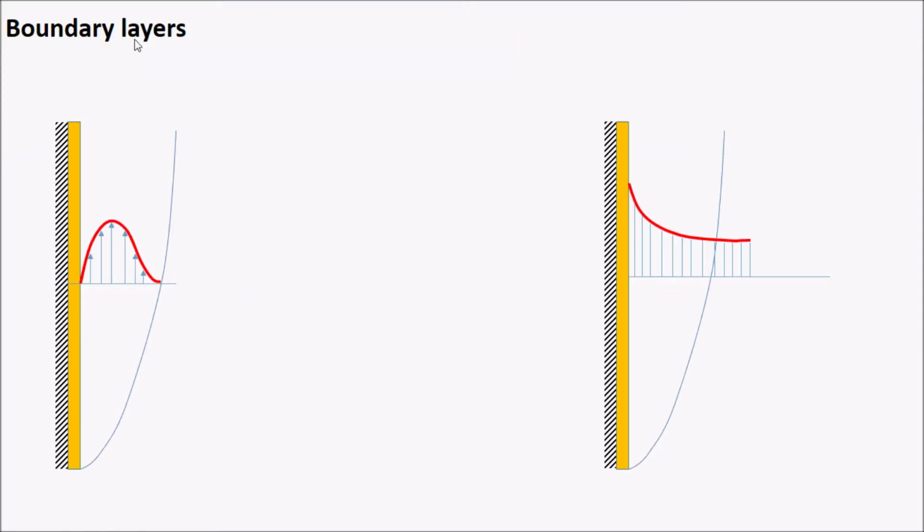So now we'll look at the boundary layers for free convection, and as always we will have the boundary layer that develops on the surface, which is hot here, or it can be cold. In this case it is hot. You have the growing boundary layer, and at some place you have the maximum velocity. Here you have the two minimum velocities. The difference from forced convection is that in this part you have the quiescent fluid, which has T infinity, but U infinity is 0.